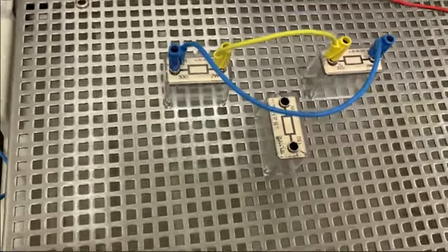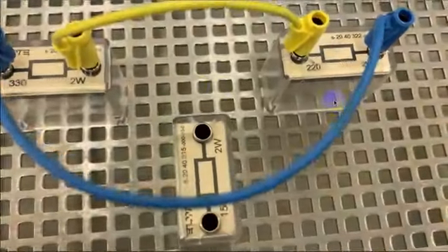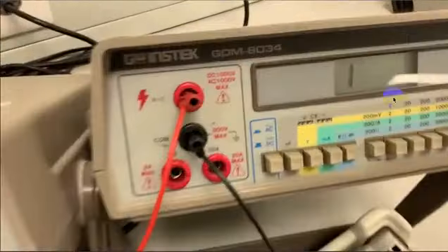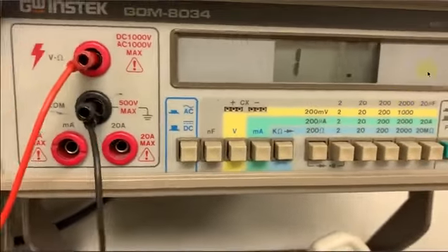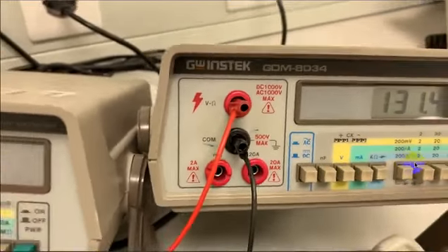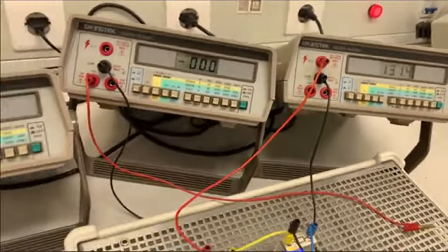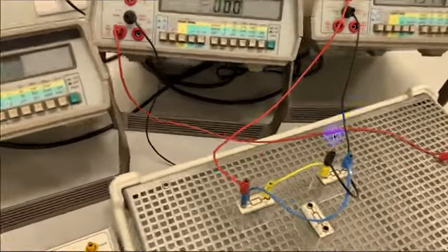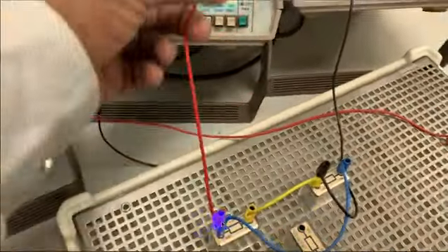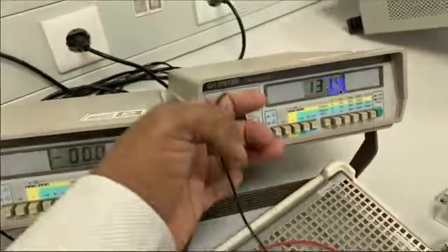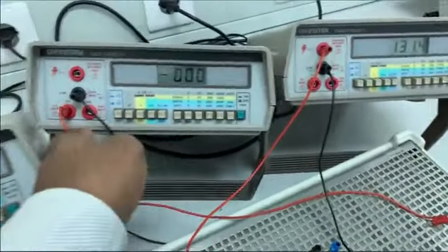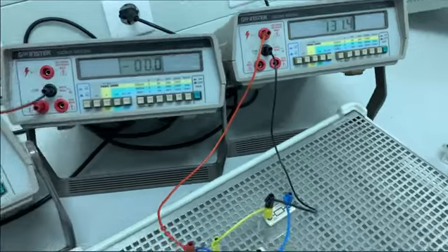So connect the ohm meter at any two points, 330 and 220. Just keep it on kilo ohm, not in the volt. Now let us connect the ohm meter here and here. So now the total resistance is 131.4. So 131.4 is R Thevenin. So we calculated here V Thevenin and R Thevenin.